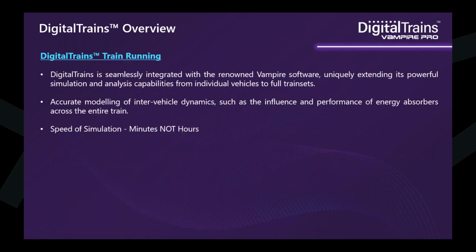For train running simulations, Digital Trains is not only simple to use with a smooth interface, but it's also uniquely integrated with the proven Vampire software and extends those capabilities from just simulating individual vehicles to having the ability to simulate full train sets, complete rakes. This means we can accurately model the inter-vehicle dynamics, including how the energy absorbers behave across the entire train. And one of the standout benefits here is speed. So we're talking simulation results in just a matter of minutes, not hours.